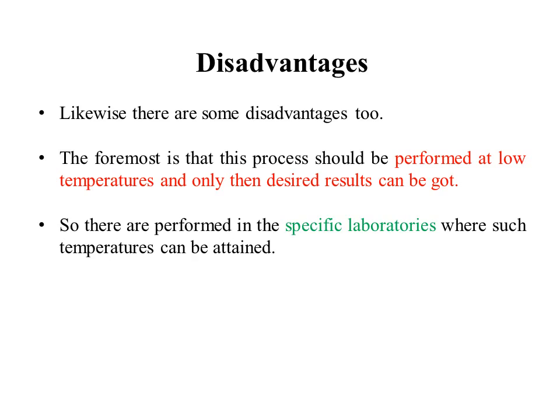And the other thing, its detector is also sensitive. So this instrument needs a continuous supply of maintained temperature, because temperature fluctuation can damage the detector or can also result in spectra which are not resolved.